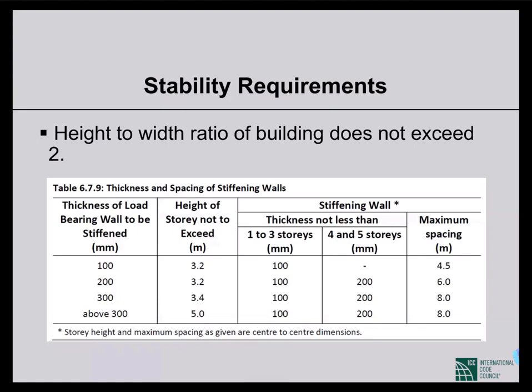So admixtures are not necessary, but if you want to have pumpable grout, then you can use a superplasticizer to have more workability, right? But to manufacture hollow concrete block, I don't know what type of admixture is used. We'll follow BNBC load combination to design masonry structure and reinforce.